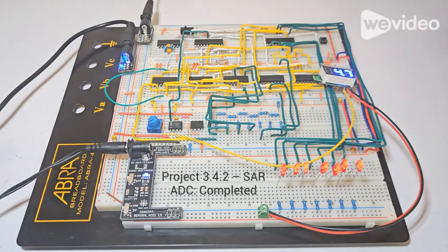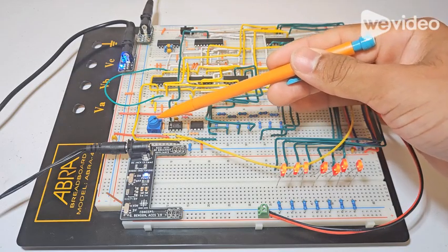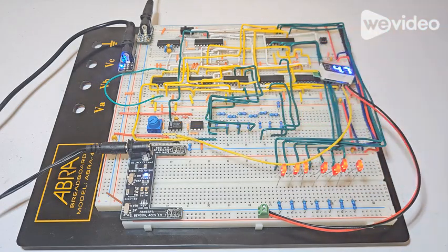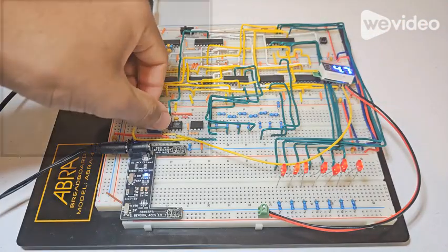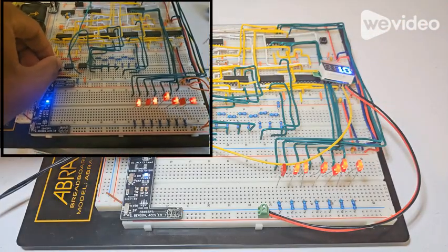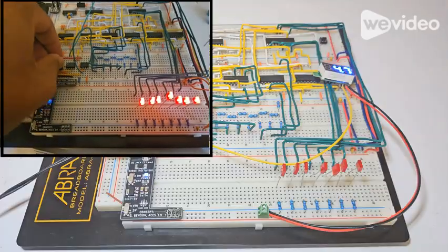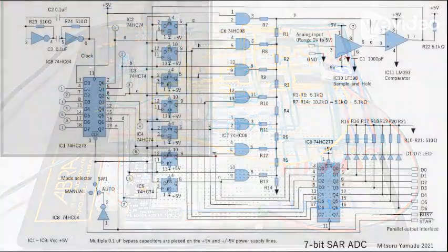This analog to digital converter takes an analog input, in this case a potentiometer, and converts it to a digital binary representation, these LEDs. Unfortunately, due to leakage in my sample and hold IC, it does not properly display the binary representation of an analog input as seen when I turn the potentiometer, but on screen there is a video of when it works to an extent.